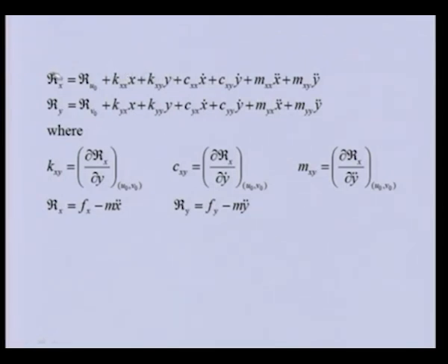This is the fluid pressure, and these are the static forces in the horizontal and vertical directions. These terms are for the Reynolds equation, because we are not considering the fluid inertia. These terms are generally present when we have very high velocity of the rotors. These are called mass coefficients, so stiffness, damping, and mass coefficients. The Reynolds equation does not take care of this particular